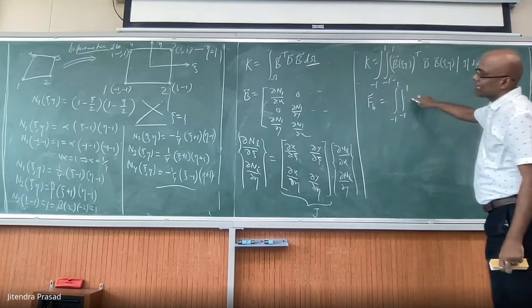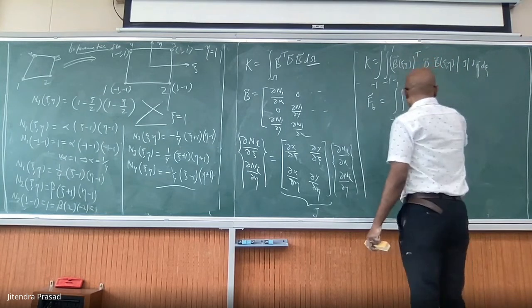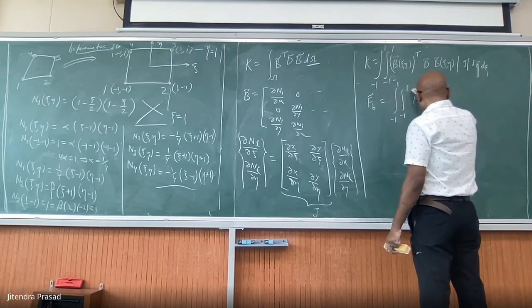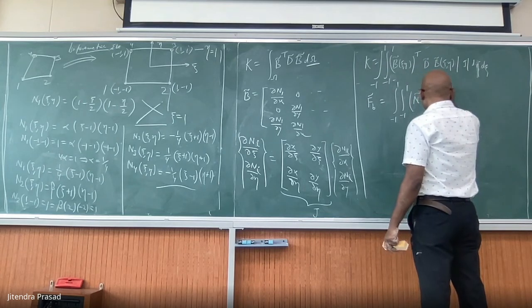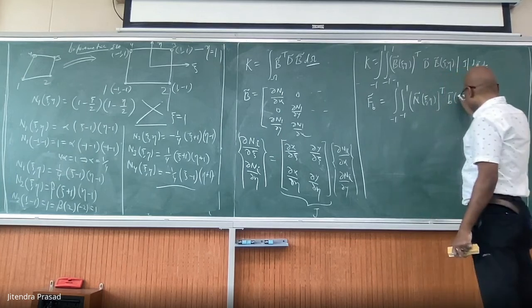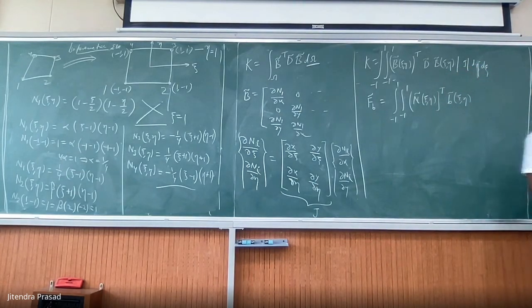And then you have here the N matrix. N itself you already have in terms of xi eta, so take the transpose of that, and then the body force b you also have to convert in terms of xi eta now, from the xy system into this system.